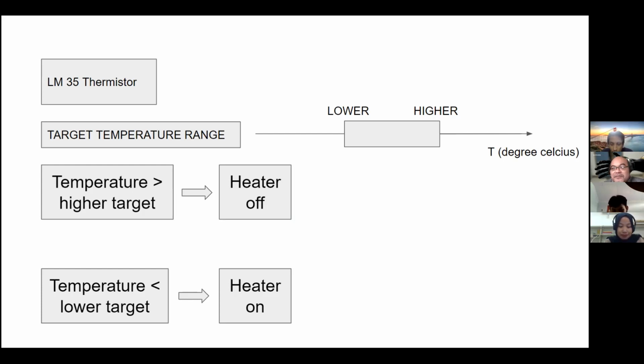Based on the current changes, let's say when you touch the heater, you introduce the temperature of your body, right? Then due to the temperature, the resistivity of the heater will change. So the current will change as well. Then you use your Arduino to control the flow to maintain constant current, for example.